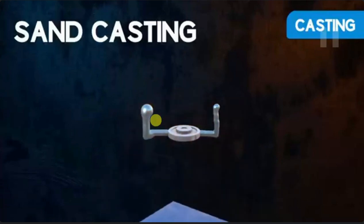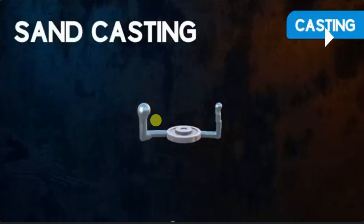Basically, as the name indicates, in sand casting we use molding sand. Using a molding box, we ram this sand. One is called the cope box, one is called the drag box. Finally, we assemble them, and we put in risers, a gate system and so on. That I will discuss in depth in the next video. Then we pour the molten metal, allow some time to solidify, and finally we break down the molding box and get a cast product like this.